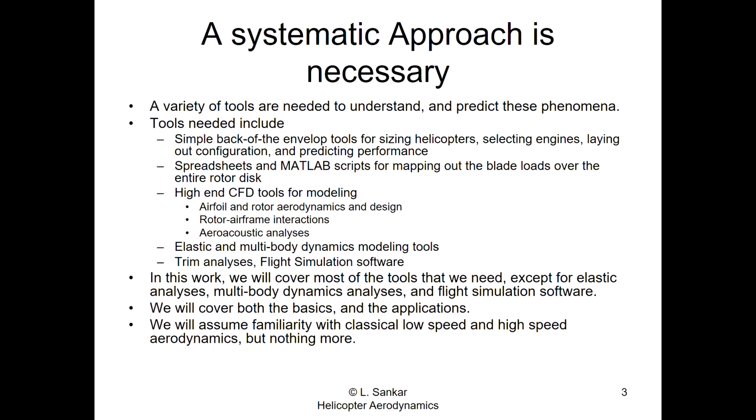to solve the problem. Then once you have gotten the sizing done of a helicopter, and some of the preliminary components are designed, and you want more precise answers, then you'll go to high-end CFD, perhaps the aerofoil aerodynamics, perhaps the rotor aerodynamics, perhaps to model the rotor airframe interaction. Then you'll take the pressure distribution over the blades, pass it on to an aeroacoustic analysis to produce the acoustics analysis.